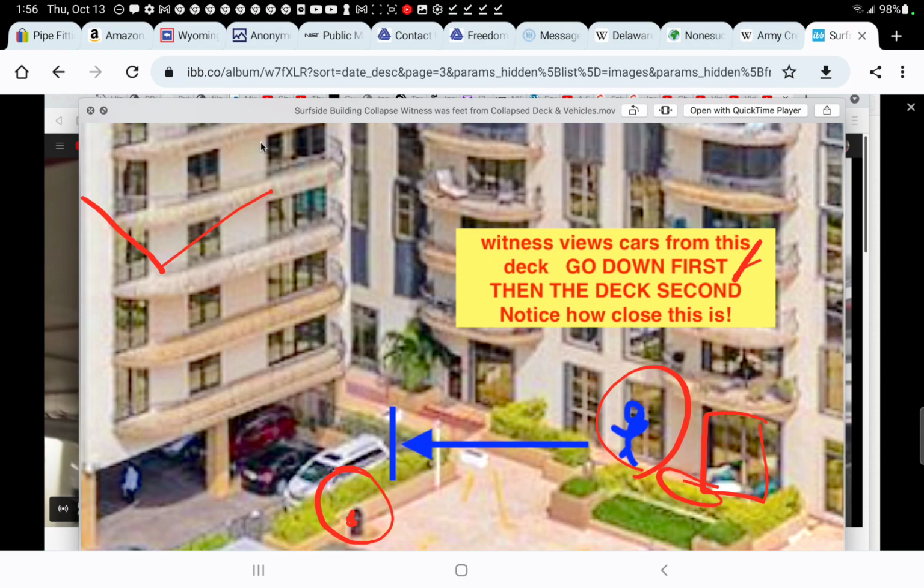Remember, I talk about the slab behavior and the upper covering slab, and it is secured only up to the columns here. But over here at the deck, for example, say I can't see it, but there's a column there that goes over the deck. It straddles over the deck, but around here, it butts up. So you're getting all this weird behavior where you're getting some support and then tributary, and then it's just a dead load where it meets or comes up to columns that it does not straddle.